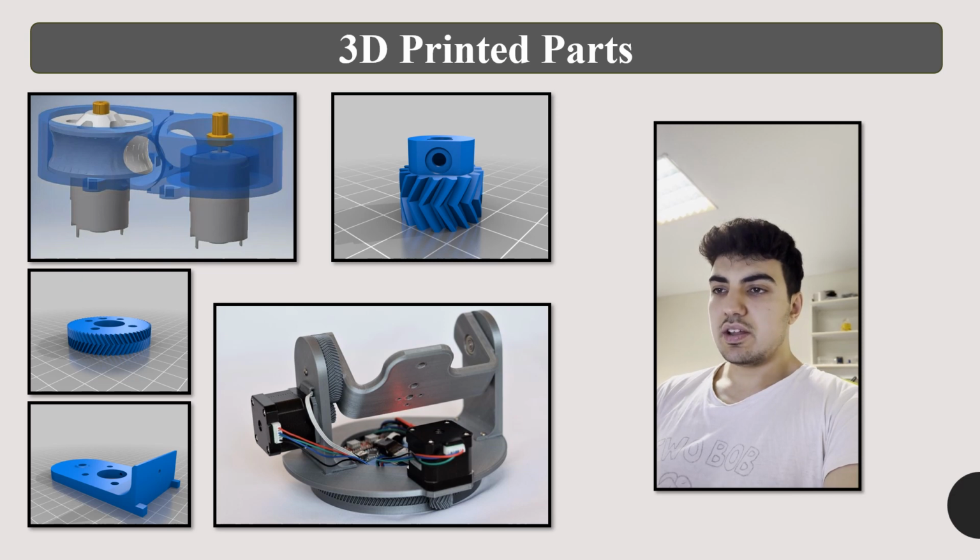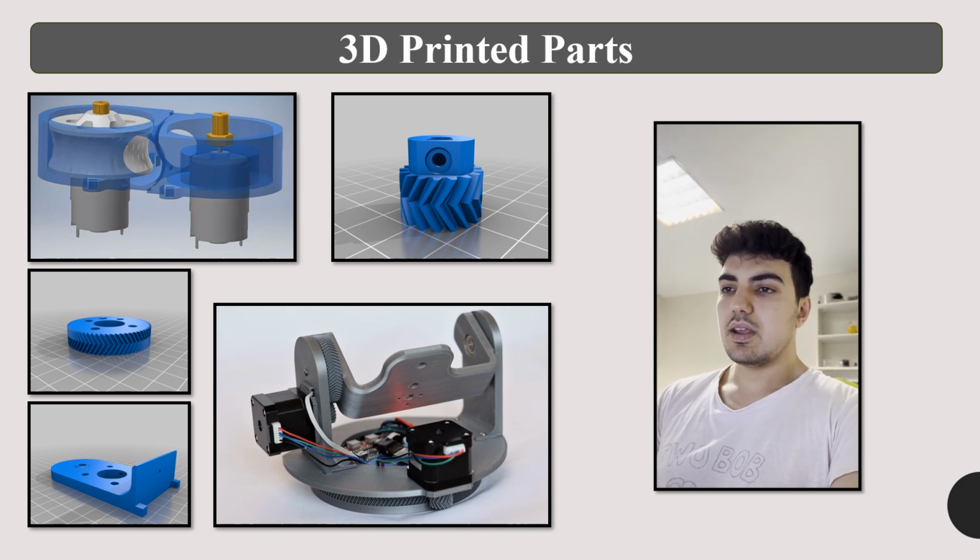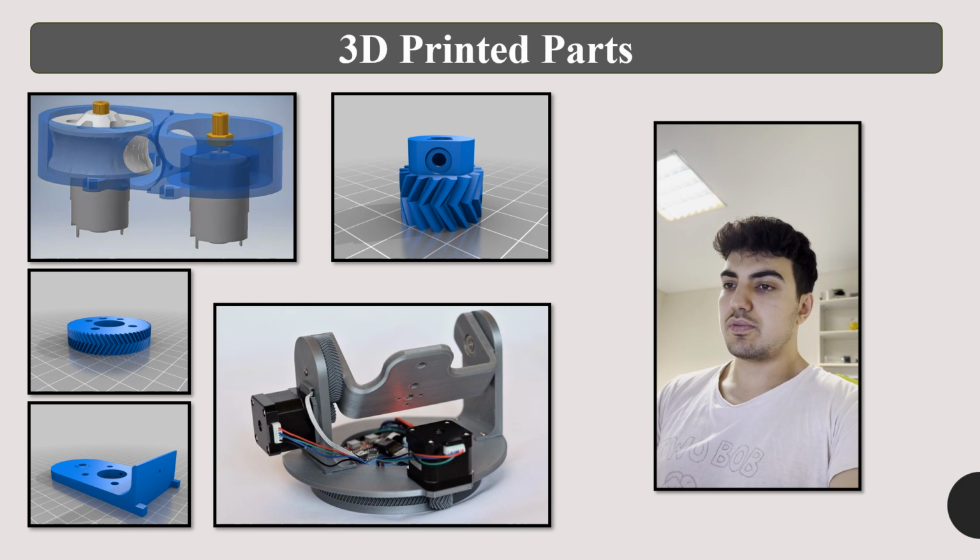The capability of 360-degree rotation is needed, so to improve the movement of the system and to decrease friction, a bearing is printed and used. Inside the bearing, there are small plastic bullets. Also, a magazine mechanism is needed at the back of the launcher, because our weapon should fire in a single shot or multiple shots. A rack and pinion system is used for the magazine and it can load up to 6 Nerf balls.